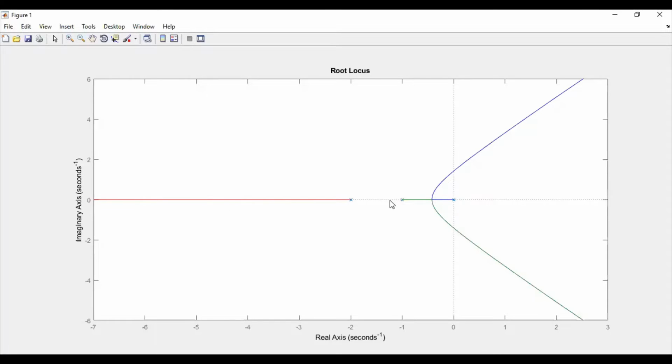So asymptotes are reference lines to give you a hint about the shape of the root locus. They have nothing to do with the root locus itself. Now, what question he asked is, if I take another breakaway point, what is meant by overlapping? I am speaking with respect to overlapping of root locus branches.